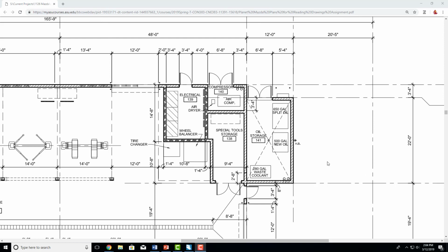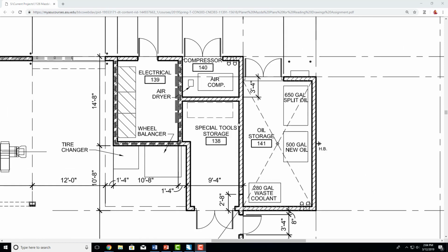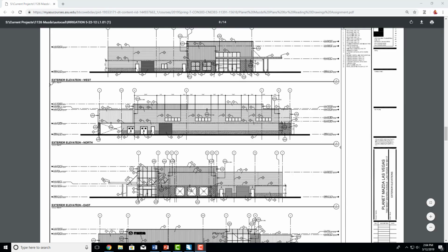If you look closer here, this is the same material designation I was talking about earlier. A 45-degree line will always mean masonry, meaning this is a masonry building. This darker line around this area will indicate fire protection is needed because this is an electrical room and that's where they're most common.